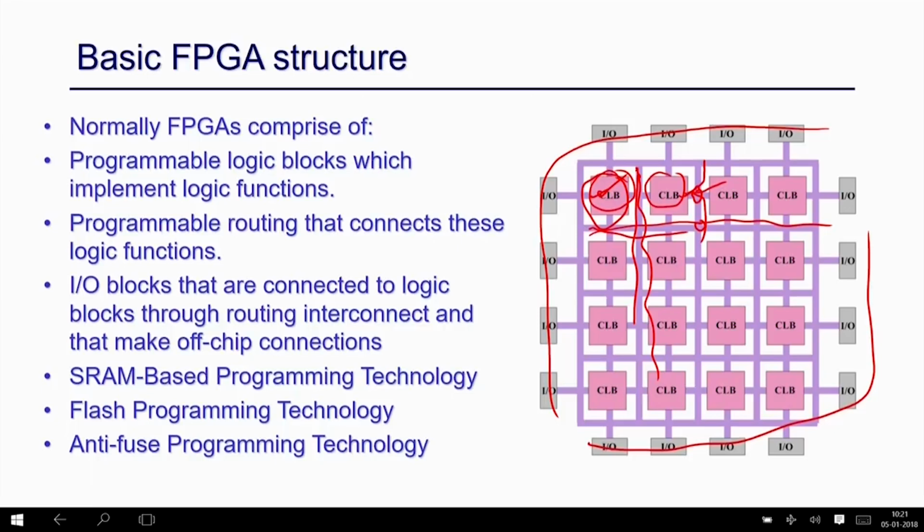Primarily, these programmable components are mapped through SRAM based programming technology. In some scenarios, this can also be flash based programming technology or anti-fuse programming technology.